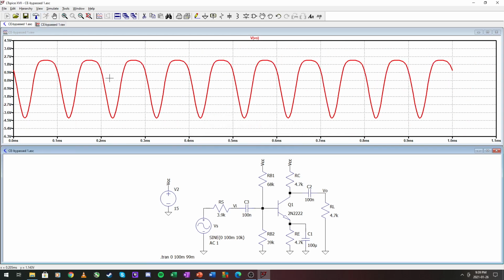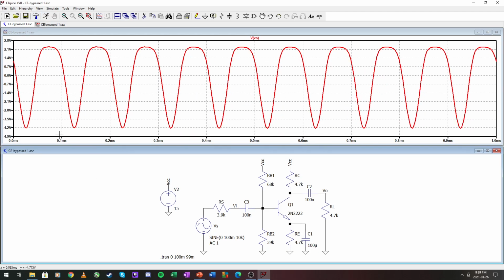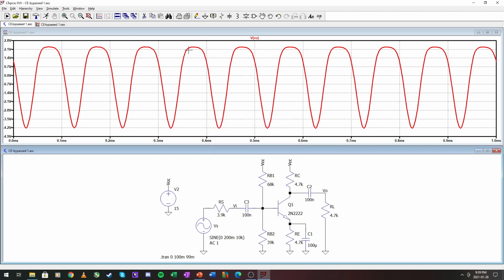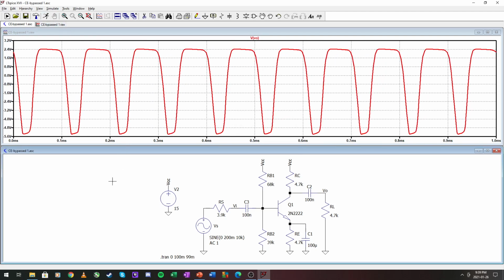If we put in 100 here, it will have clipping on one of the sides, so we can just drive this on and on, and there is our clipping, and we can see our maximum outputs with the load attached that we did calculate if we just drive this input really hard.